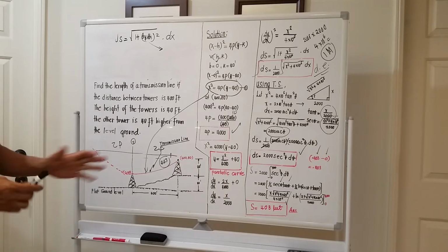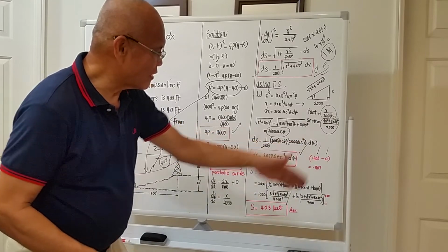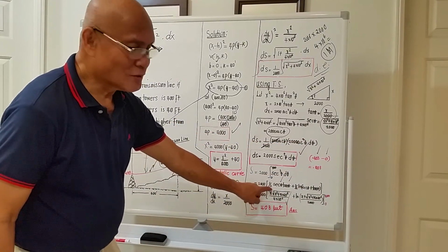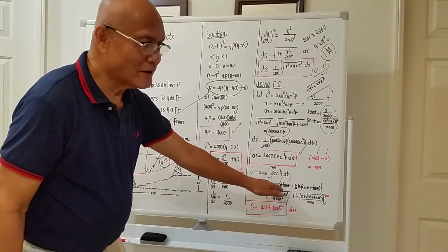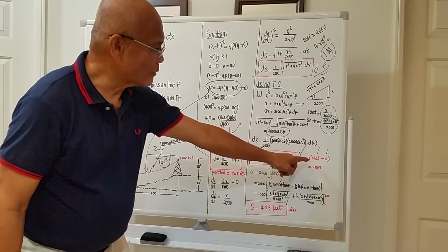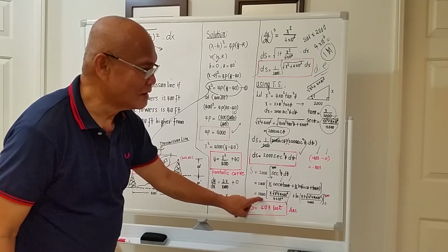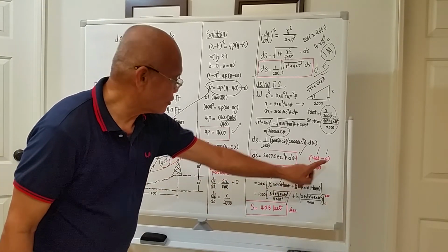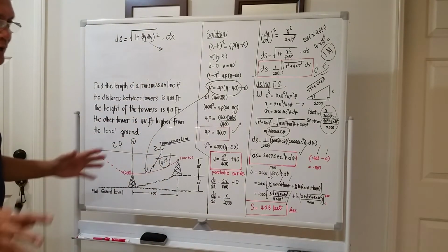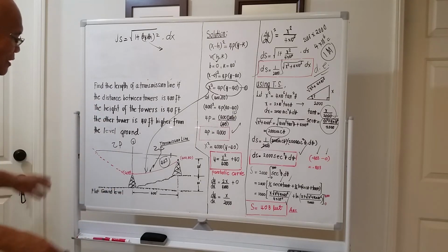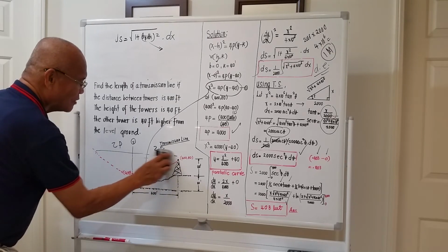Okay? The solution is a little bit complicated. I expedited it, but I've shown you the steps. On the substitution of this one, I told you use your rough draft, use your calculator, try to solve for the value of the upper limit, then subtract the lower limit. What will come out will be 0.403 minus 0. It is 0.403, but this is to be multiplied by 1,000. So 1,000 times 0.403 will be 403 feet. That is how we compute the length of transmission lines using integral calculus. That is, if the level of the towers are not actually at the same level.